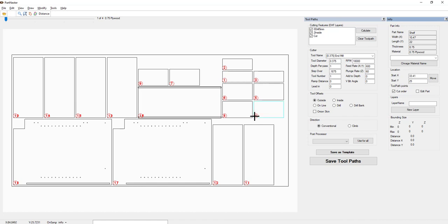This isn't necessarily by default the way we would want it for cutting if we do not have a strong enough vacuum. You want to think that we'll be cutting in a conventional pattern, which is left to right, so we will be going around the part anti-clockwise on the outside.